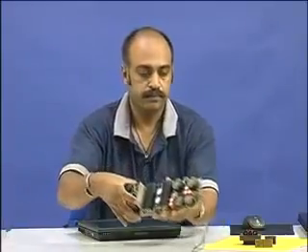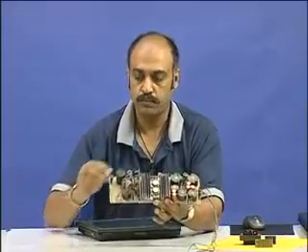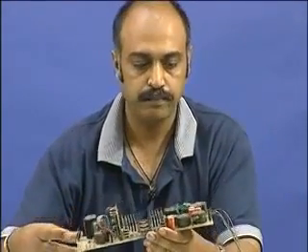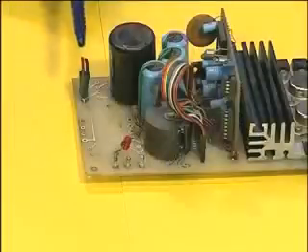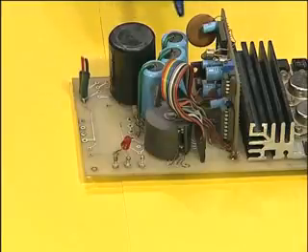Let me show you a typical power supply board, and let us try to identify the components and see how it is placed in the PCB, so that you get an idea of the various components that go into a practical circuit. Now, this is a practical printed circuit board. This is in fact an SMPS, a working switched mode power supply. Okay. We have the outputs, and here is the input. This is followed by a capacitor, this is the aluminum electrolytic capacitor. Here you see 3 capacitors, which are the non-polarized capacitors.